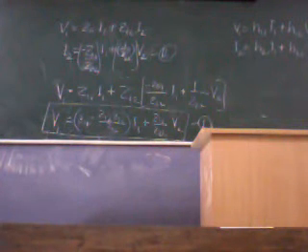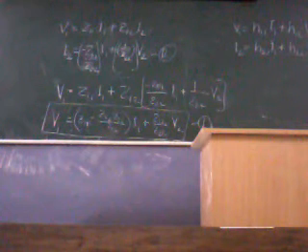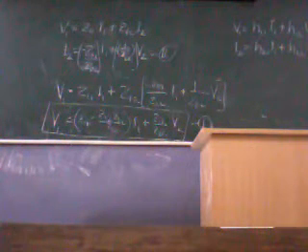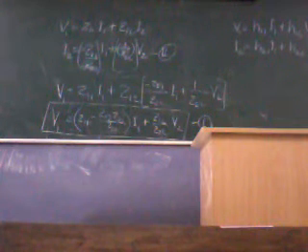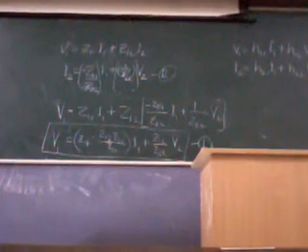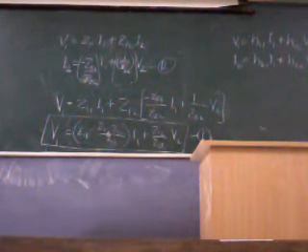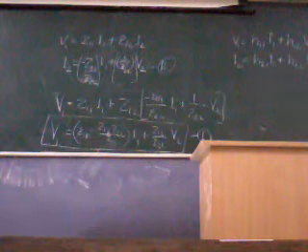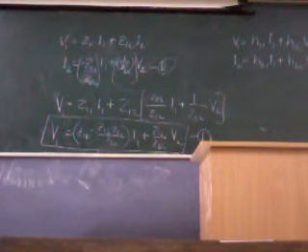So then very simply you can write h11. What is h11 then? Z11 minus Z12 Z21 upon Z22. What is h12? Z12 upon Z22. What is h21? Minus Z21 upon Z22. What is h22? 1 upon Z22. Is it alright?